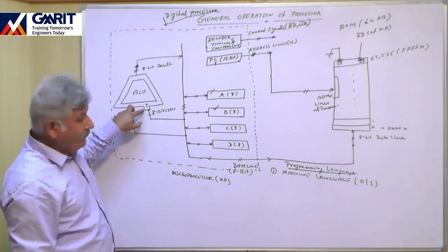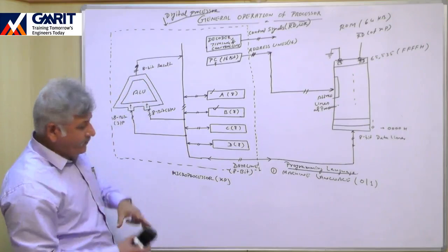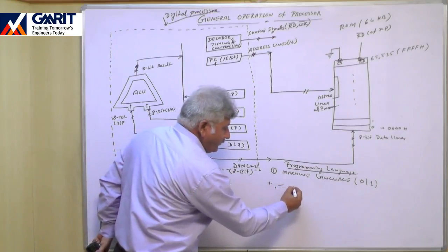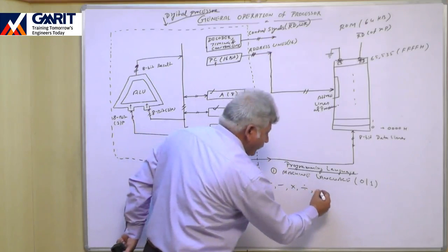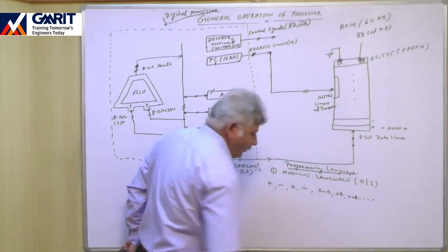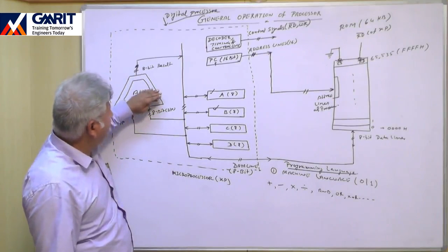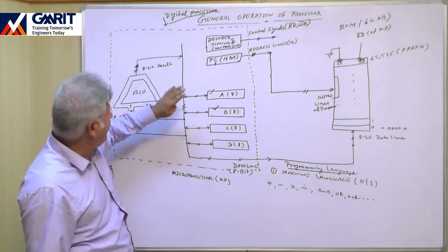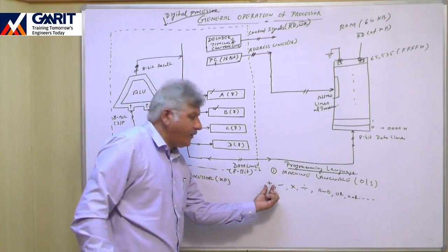Now these two numbers are available here. Now inside the ALU, we already discussed that we can perform operations of addition, subtraction, multiplication, division, or we can perform logic operations like AND, OR, XOR; many operations can be performed. So inside this ALU, the designer of this particular processor has already fabricated one 8-bit adder section.